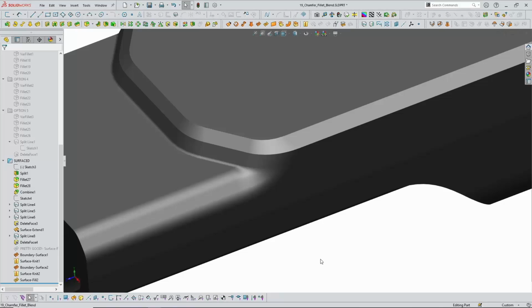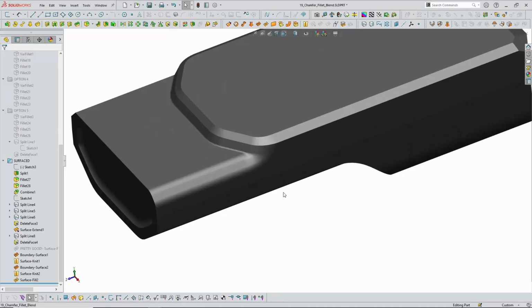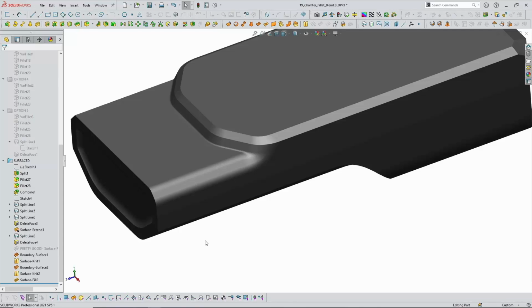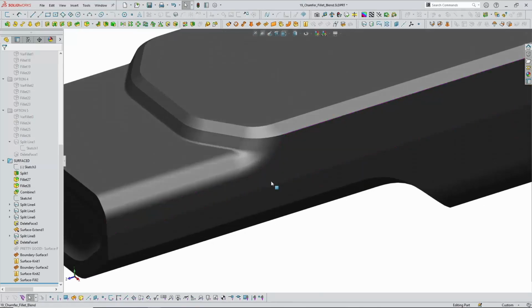They're not necessarily bad. This is a very utilitarian product used by law enforcement. We wanted to have that look that it was a little bit more intentional, a little bit more of an institutional style product rather than a very sculpted, smooth, seamless consumer electronic. And that was a decision that the design team made to be able to have this product look a little bit more hard-edged with its radii. And ultimately, this transition was exactly what I was looking for, but I did have to sculpt the final corner with the surface tools rather than rely on the fillet tool to get me what I needed.